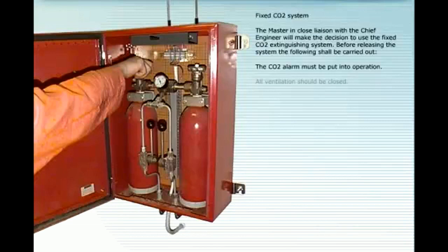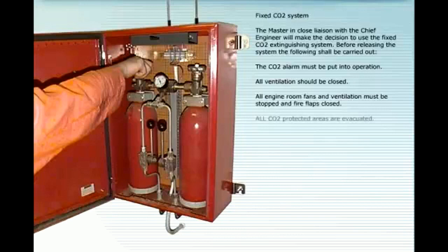All CO2 protected areas are evacuated. The engine room, paint shop and incinerator room must be completely evacuated and ensure that all personnel are accounted for. The system shall only be released on the master's order.